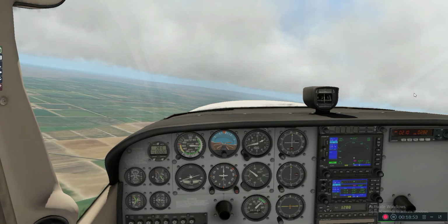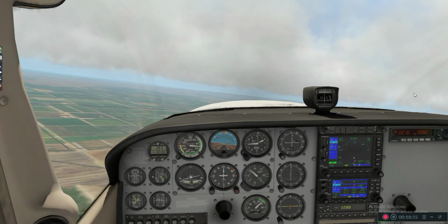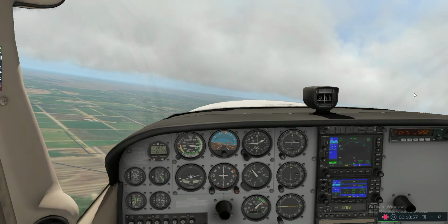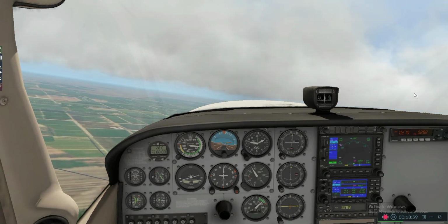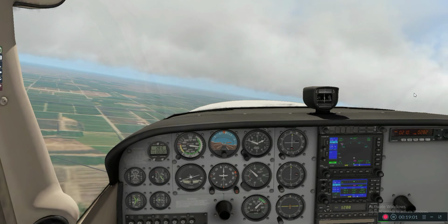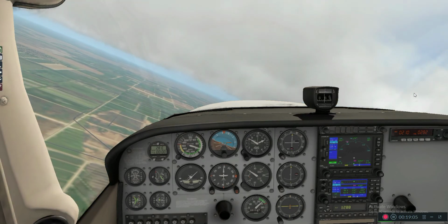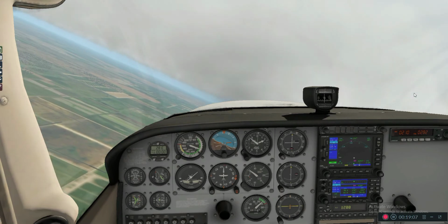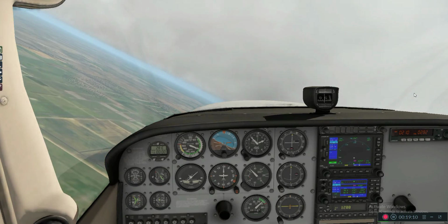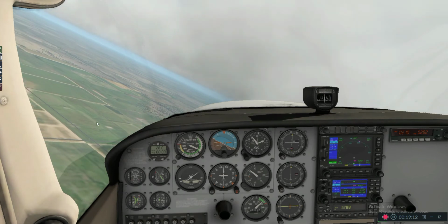And I like to wait to take the last notch of flaps out. There's no rush on that with that 10 degrees of flaps. So we're all the way up at VY now. It's a great time. The last notch of flaps is out. Very simple stall there. The behavior is consistent with a real 172. They've done a pretty good job with this thing. I'm pretty happy with it.